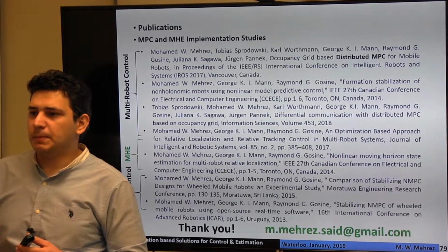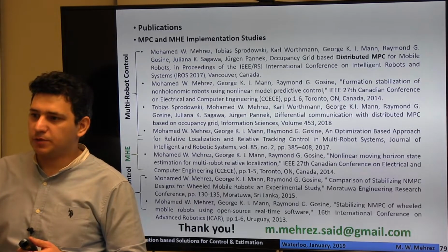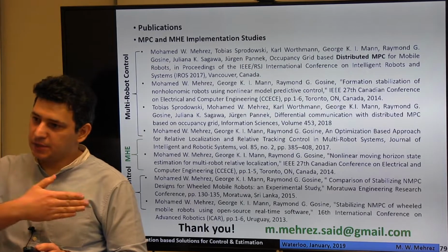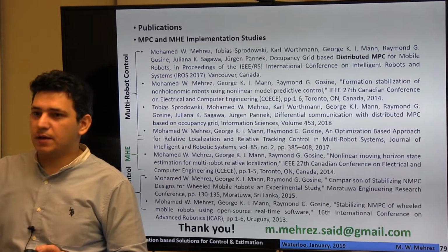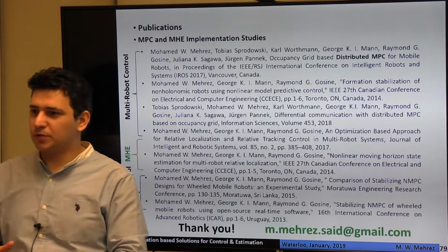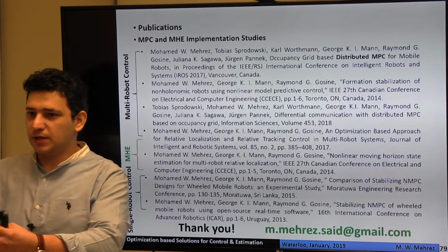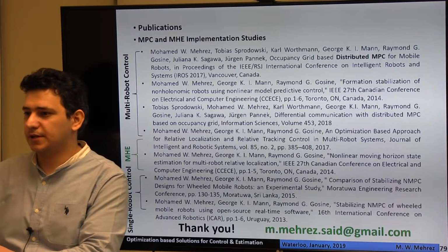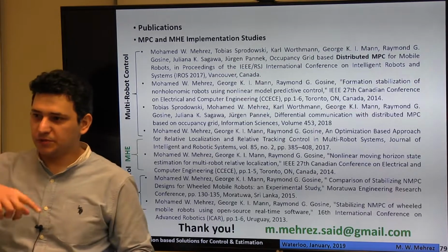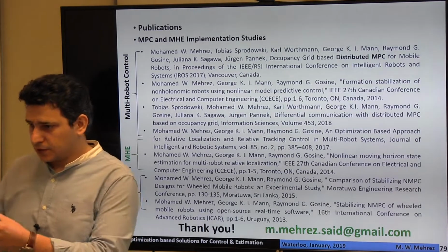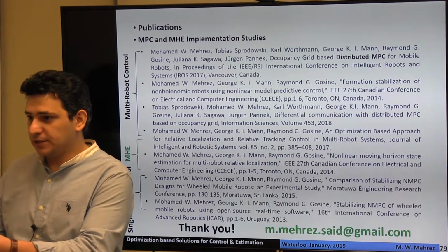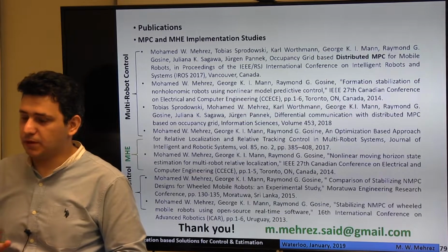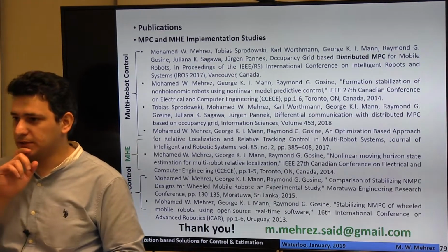You can, it depends on the feature that you would like to capture from the LiDAR. So your LiDAR gives you, for example, 180 measurements. So maybe you can put a tower on your robot that has the shape of a circle, and you fit the LiDAR data that looks like a circle, and this will be your measurement. Because you will get your LiDAR data, right? So if one part of it fits a circle, this will be your robot position as seen from the LiDAR, or your landmark position as seen from the LiDAR.